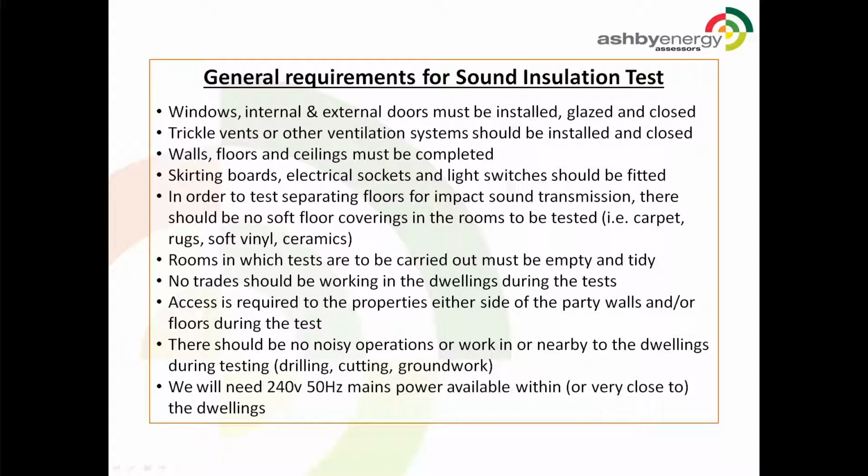Rooms in which tests are to be carried out must be empty and tidy. No trades should be working in the dwellings during the test. Access is required to the properties either side of the party walls and or floors during the test. There should be no noisy operations or work in or nearby the dwellings being tested. That includes drilling, cutting or major groundworks. We will need 240 volts at 50 Hz mains power available within or at least very close to any dwelling being tested.